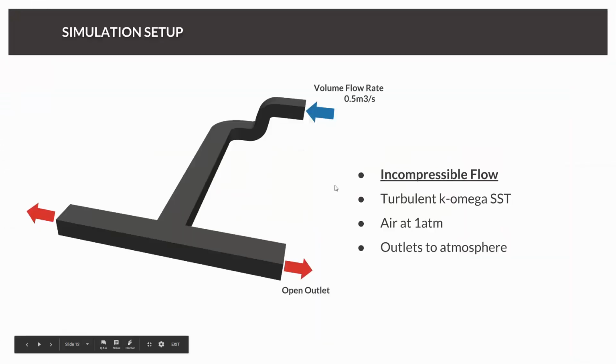And this is actually the first very important learning. All these analytical methods used in the past are not necessarily bad, but they have limitations. Whenever it comes to more complex changes of the shape of your HVAC system, or to explain it more generally, whenever it comes to big changes in the physics of our flow field, these models are not anymore able to predict the pressure drop accurately. A very good example for that is a flow separation.